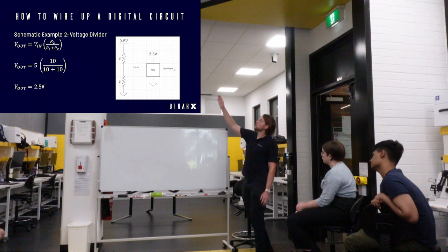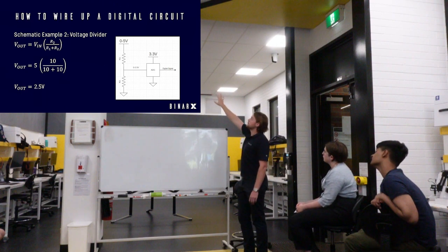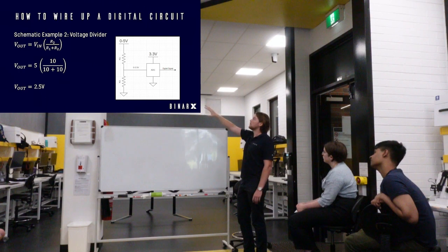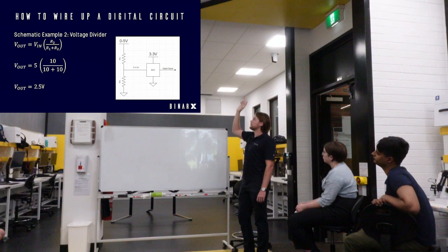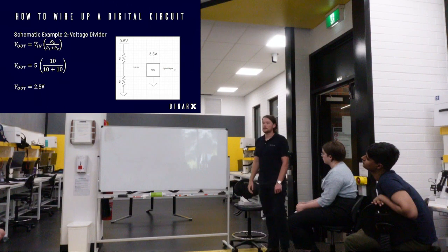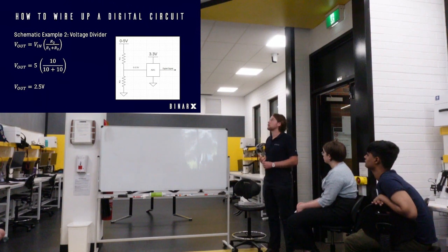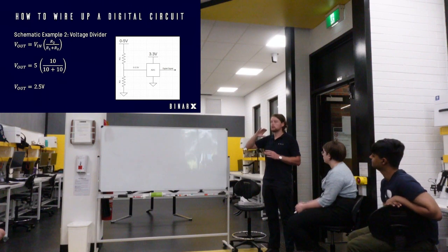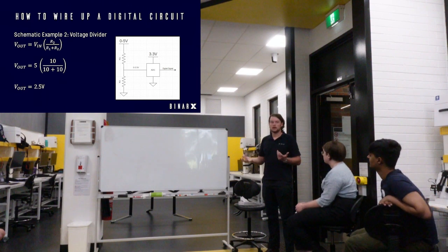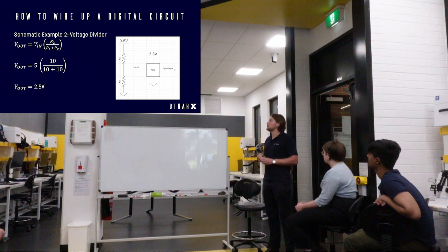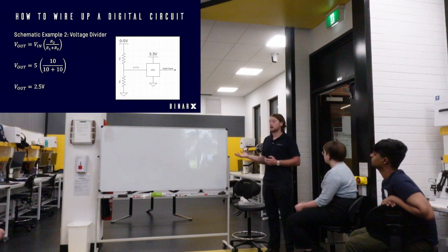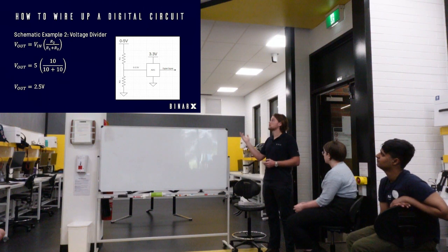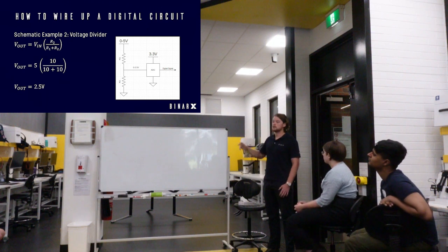So if you want, you can think about it that this ADC, the digital signal, is all part of a computer, and we're inputting a digital signal into it. But what commonly happens is that our microcontroller runs on 3.3 volts, but the signal that we're reading in is from 5 to 0 volts as an analog reading. So that changing value, if it goes above 3.3 volts, we input 5 volts into our microcontroller, it can break our microcontroller. So we use something called a voltage divider circuit to essentially step down our voltage so that our ADC can read it better.